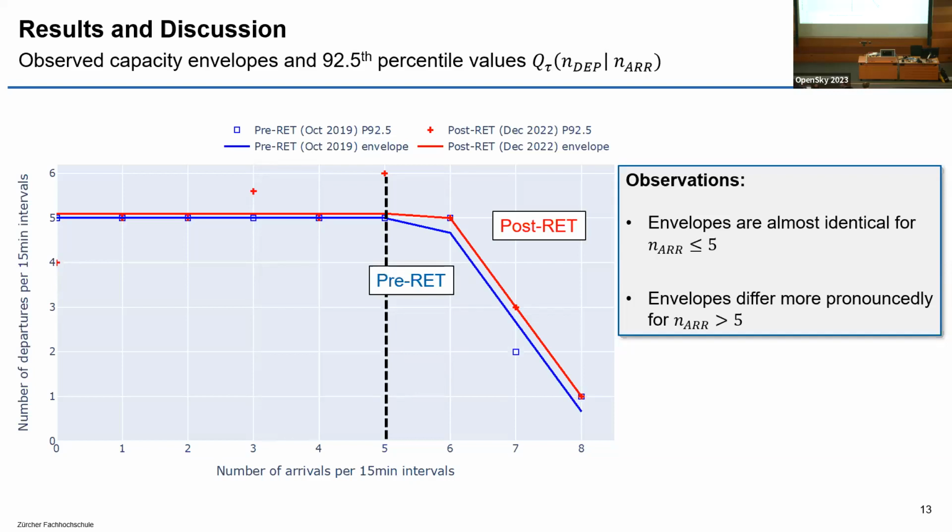The impression I have with some of the things you are telling right now is that for sure, making RETs at the airport increases capacity. We do that exactly for increasing capacity, reducing runway occupancy times. That's something pretty obvious. Except, and you have shown in one of your graphs, if the operation of the airport changes because of COVID or because of the evolution of time, then the comparison is a bit useless, because it depends on the fleet mix at every specific moment, on how the aircraft operators operate, and on how clear the instructions to the pilots are to try to use one specific exit taxiway and things like that.